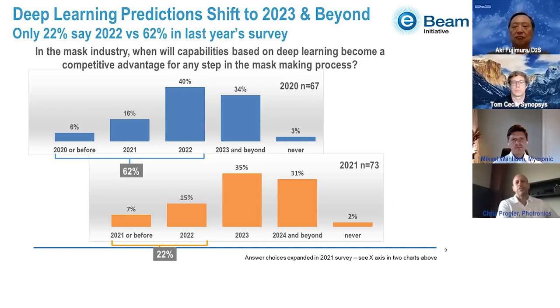But the mask industry lags in this. Even MPC, mask process correction, is only now being, I would say, fairly widely adopted. And it's relatively simple compared to OPC. And there's still a lot of reluctance, so I think we have to be pulled along in here, and that's going to come through collaborations and those sorts of things, and how to implement this technology in mask manufacturing.